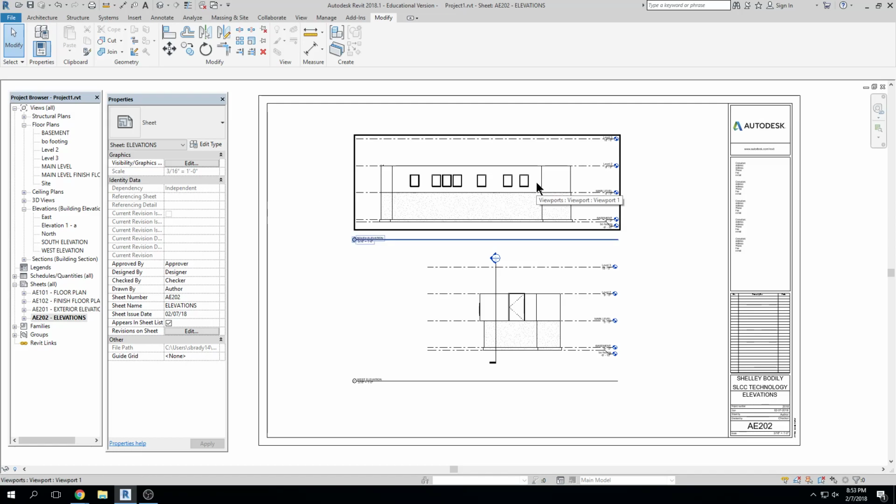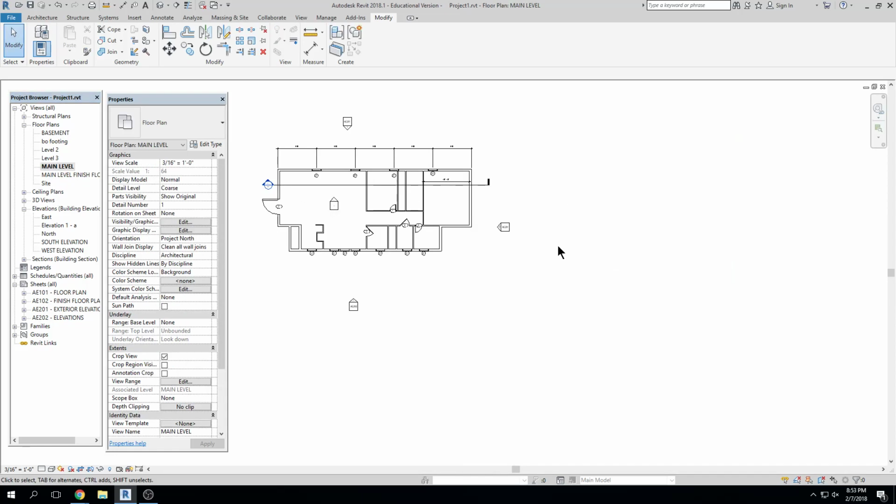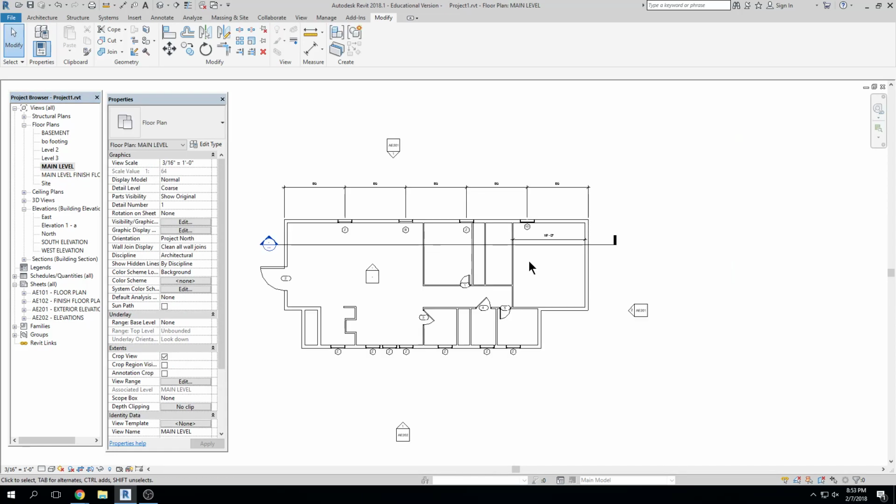I have a question. Say you wanted to rotate one of your drawings like 90 degrees. How would you do that? So let me give you some general advice in Revit. When you start drawing your floor plan, draw it in the orientation you want, because it is very difficult after the fact to take an entire model and all of the annotation, dimensions, and the site, everything involved with the model, and rotate it. So best advice, number one, just draw it the way you want it.